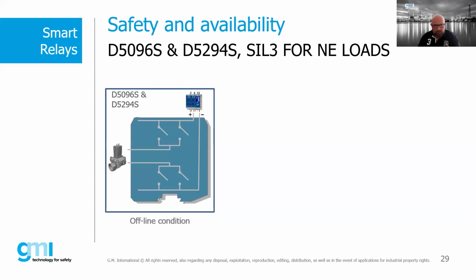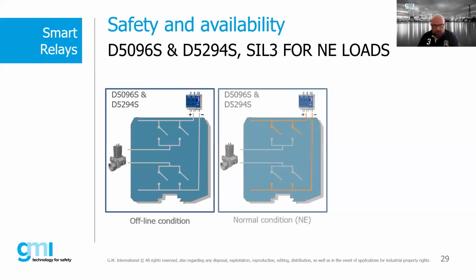When we talk about availability, we are defining the proportion of time for which the equipment is able to perform its function. Availability is different from reliability because the latter takes into account the repair time. For example, a device may not be very reliable, but it can be repaired quickly when it fails, and so its availability can be very high.